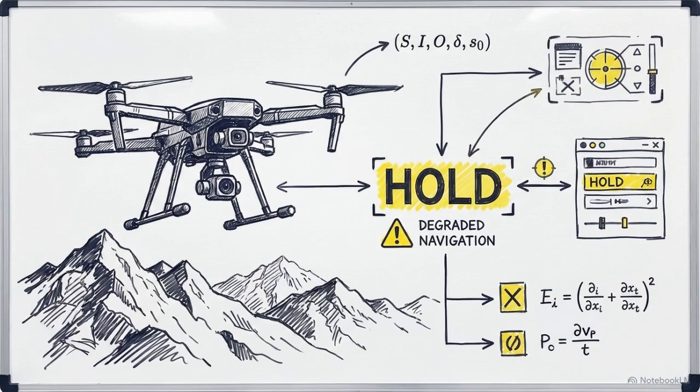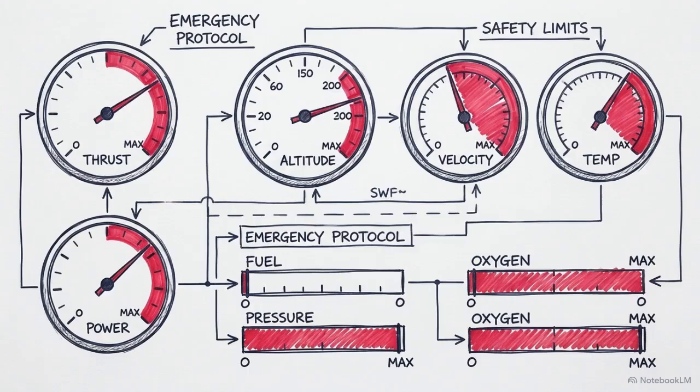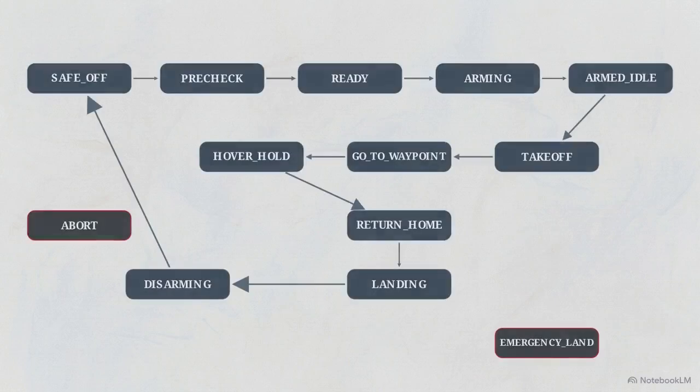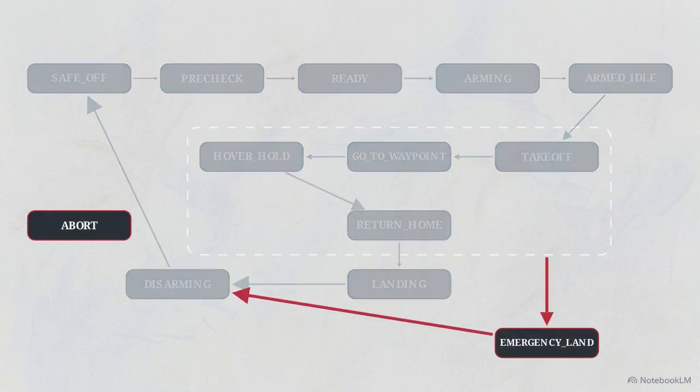an immediate mission failure. For critical failures, the FSM uses global interrupts, high-priority safety rules that override the current mission state. Scenario S3 represents a severe onboard fault, like a propulsion failure. The architecture groups all airborne states together. A critical fault can hijack the system from any point in the flight, routing it directly into an emergency land sync node for an immediate shutdown.